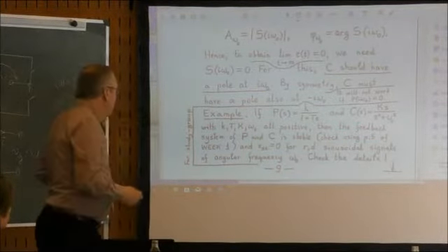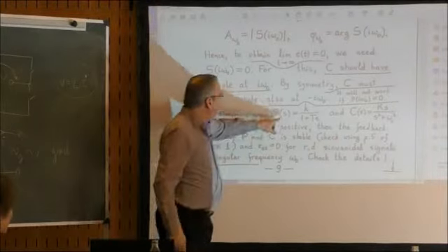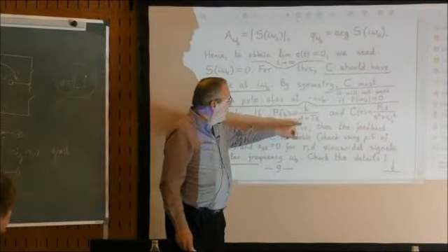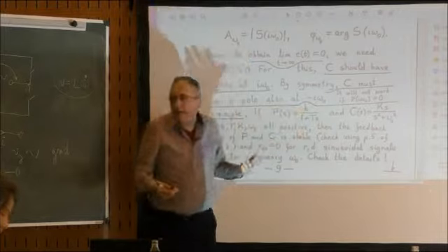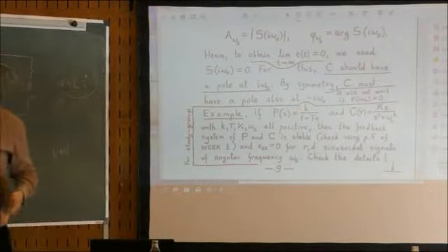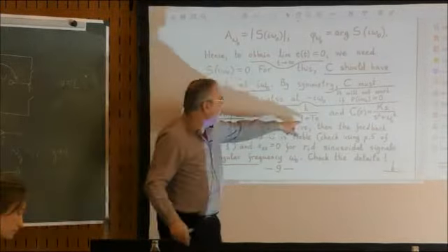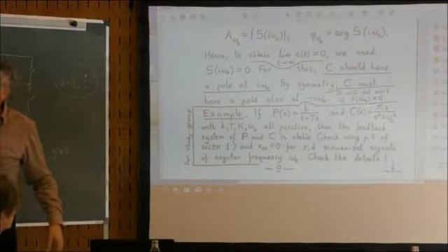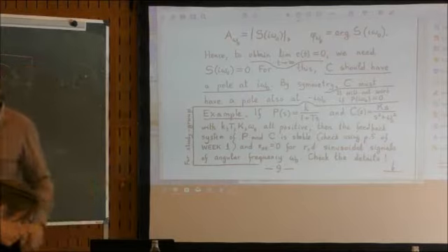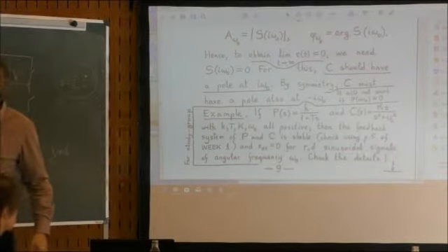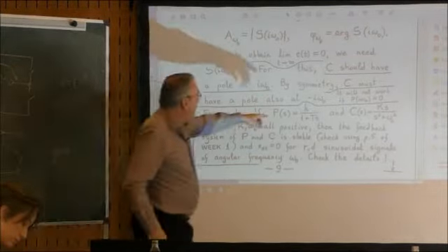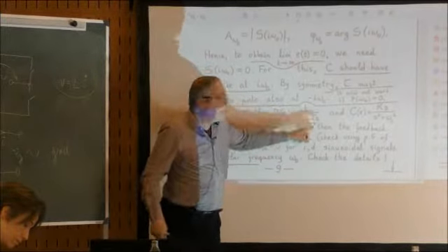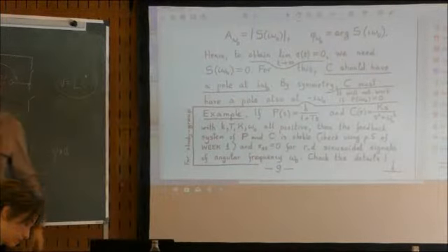Okay. So you see, this plant is a constant divided by 1 plus Ts. I can write it exactly like this, if I just divide by R. So this constant K will be 1 over R, and this constant T will be equal to L divided by R, right?